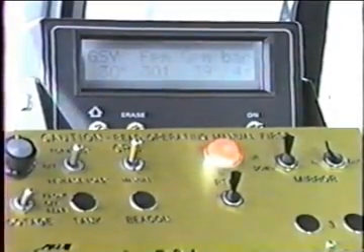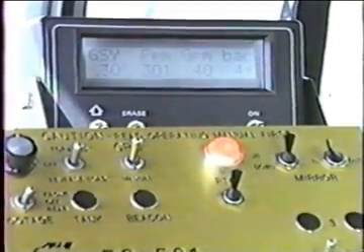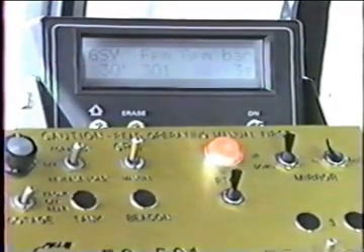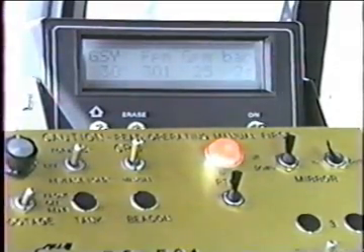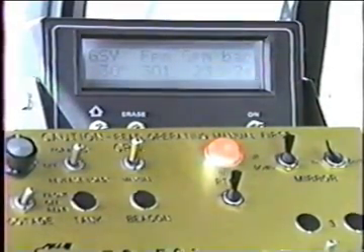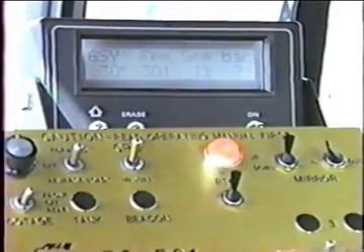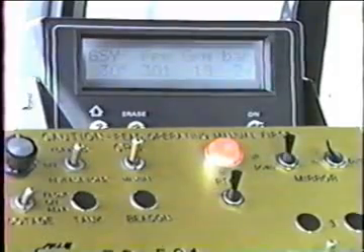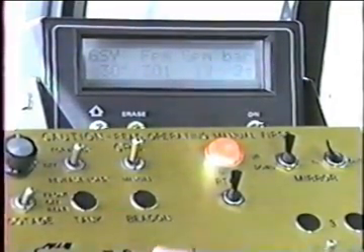When we get below 25 gallons a minute, sometimes we have a little inaccuracy. Let's see how we do today. There's 3 feet, 30 gallons a minute. 2 feet, down to 20 gallons a minute. At this low of pump speed, we'll see some oscillation because of the size of the gear teeth in the pump. It has a hard time when it gets down this slow.